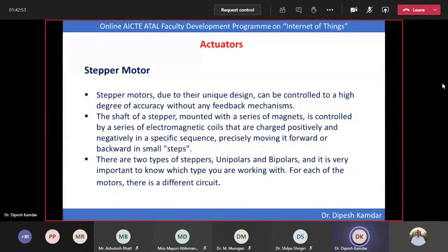Once we know what the stepper motor is and connect the wheels or any other devices to it, the number of steps it rotates and the distance it covers we can compute with the radius of the wheel or whatever device it is connected to. You can compute the perfect number of steps, and the robot you made will cover the distance perfectly.